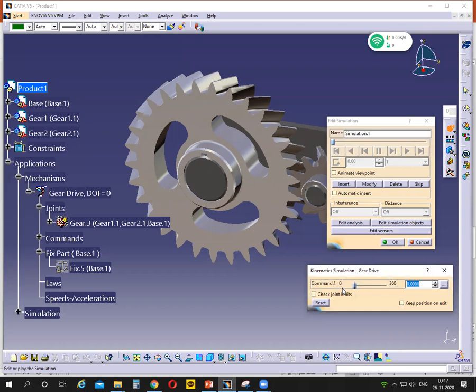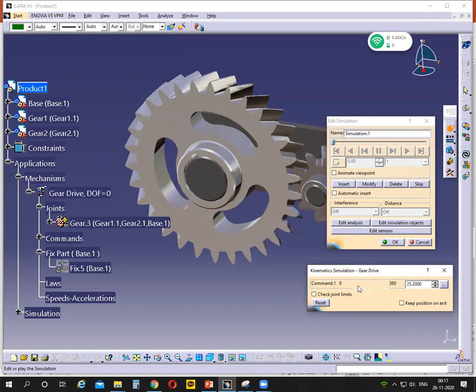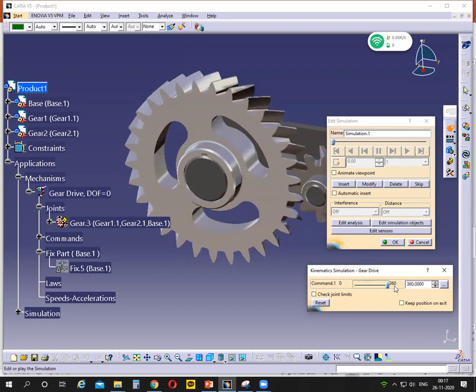Okay. Yeah, before inserting a new simulation, or to edit the simulation, you can edit. You have to check that one before, okay, whether it is working or not. Drag this side, and after that, insert, okay, and change the loop mode. I want continuous simulation, rewind. After finishing rewind, continuous simulation, and change the time step. And here, I want to click this forward button.